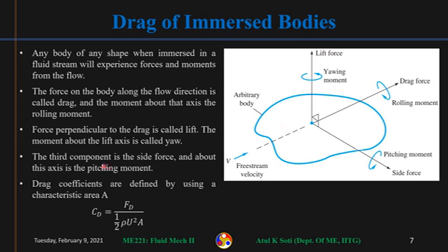And then the drag coefficient, I don't remember whether we have seen this or not. I think we saw this in the Blasius solution case, that the drag coefficient is defined as the total drag force divided by half rho u squared into area. Rho is fluid density, u is free stream velocity, F_D is the drag force, and A is some characteristic area that depends on the problem.